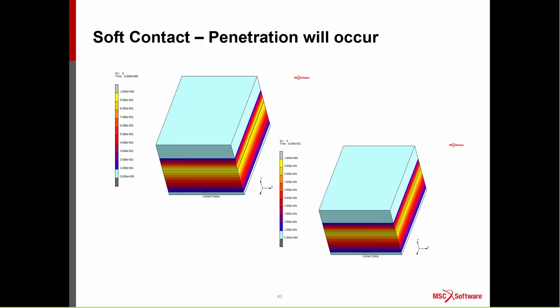One of the interesting things about introducing cohesive contact is we're really saying things are not infinitely stiff. So what you will see when you do a problem with cohesive contact, especially if you don't have a very high resistance, is you will effectively see overlap in the model. So you will see bodies that look like they penetrate one another. Some people call this soft contact.